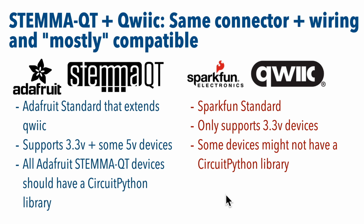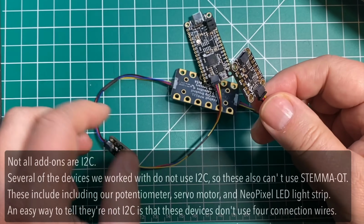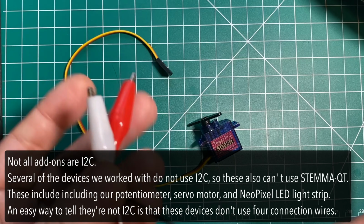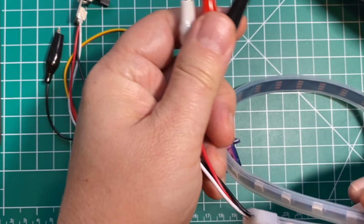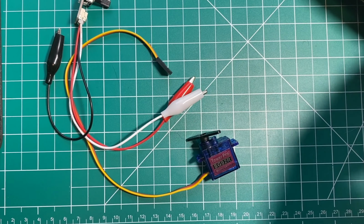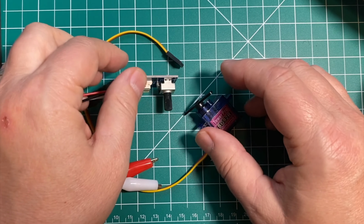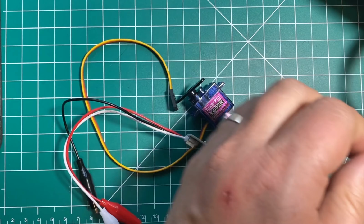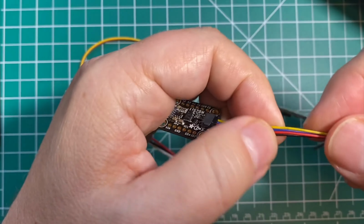Also, even though this STEMMA-QT connector is really handy, it uses the I²C communication standard, and not all the things that we want to attach to our board use I²C. For example, if you want to hook up some hardware that we used in our previous lessons, like the NeoPixel light strips and strands, or the servos and potentiometers that we'd used in our CPB lessons, these don't use I²C, so they don't link directly to the STEMMA-QT port. A dead giveaway is that these devices used 3 wires, while the I²C standard that STEMMA-QT uses 4 wires.